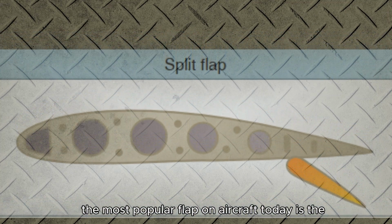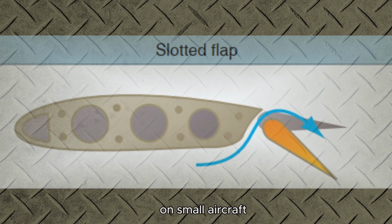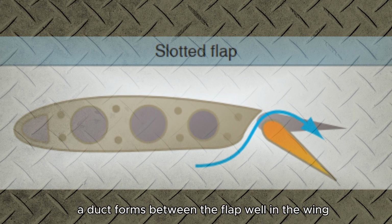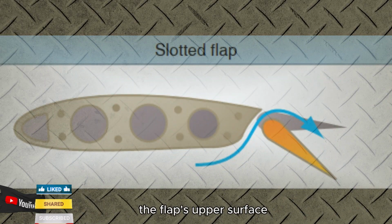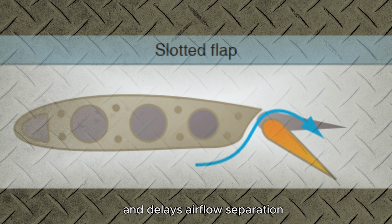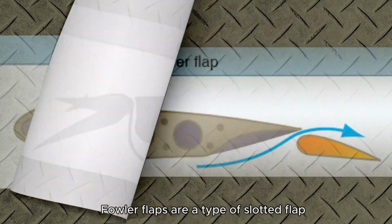The most popular flap on aircraft today is the slotted flap. Slotted flaps increase the lift coefficient significantly more than plain or split flaps. On small aircraft, the hinge is located below the lower surface of the flap, and when the flap is lowered, a duct forms between the flap well in the wing and the leading edge of the flap. When the slotted flap is lowered, high-energy air from the lower surface is ducted to the flap's upper surface. The high-energy air from the slot accelerates the upper surface boundary layer and delays airflow separation, providing a higher coefficient of lift. Thus, the slotted flap produces much greater increases in maximum coefficient of lift than the plain or split flap.